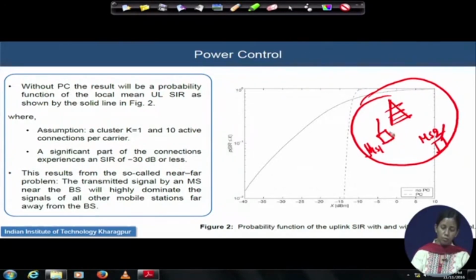having a nearby position from the base station should send the uplink power signal with a controlled low power compared to the guy who is far from the base station and wishes to get connected at the same time. So, the power transmission for both of them can never be the same, and based on their relative distance, they should control their own power to not interfere with their neighbors within a cell.